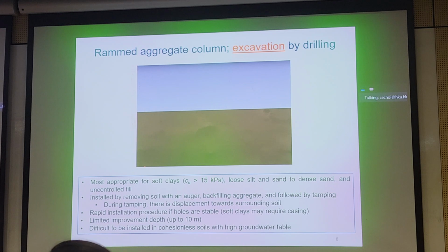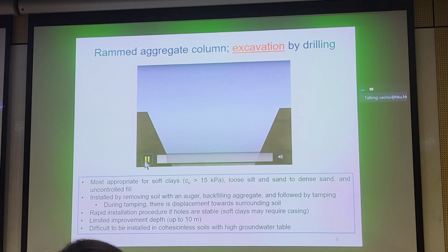The process entails excavating and removing a large volume of poor soil where the structure or footing would be. So this was the over-excavation and replacement we talked about, where it's quite costly because you need to do lots of excavation to find lots of fill material.